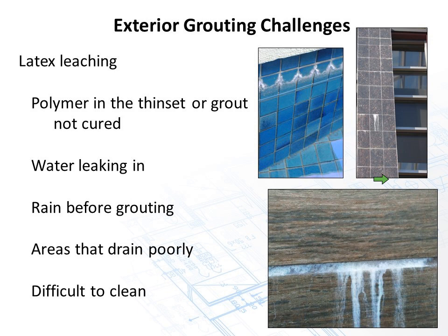It drains from the very, very top all the way down through the bottom and back out. But when we put cement board there with a waterproof membrane, there's really the only thing to allow it to drain through is a low absorption latex polymer mortar. So we're seeing this a little bit more.